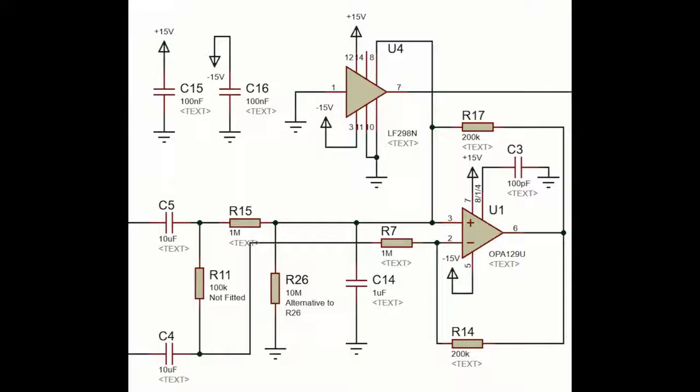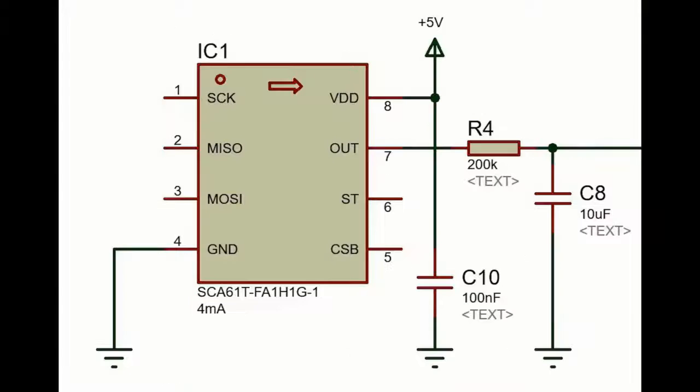We now have two signals which represent a voltage proportional to angle, one generated by the integrated gyroscope signal and one generated by the inclinometer. Both of these signals have varying characteristics. The inclinometer signal, when passed through a low pass filter, performs well at measuring static angles. It's good when stationary. The gyroscope version of this signal is really good at measuring rapidly moving angles.